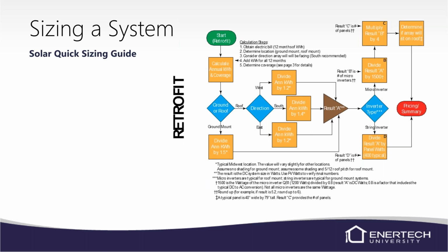You can easily use PV Watts next, where you'll validate your handwritten DC system size and double check your numbers, and you may move them a little bit back and forth, or up and down. But you don't need us to design a system. We always want to help, believe me, but you just don't need to be waiting on us to provide you the information. With PV Watts and a tape measure, you can do an awful lot.